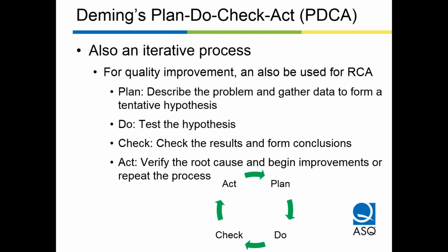And when I say gather the data, this may mean look at the SPC data out of production, statistical process control, what were the values produced over the last period of weeks, or look at the failed part itself. Form that hypothesis, or the way it often works is the team does sit down, they brainstorm, fill out the Ishikawa diagram, which for me is a collection of hypotheses, prioritize that first one you're going to evaluate, and test the hypothesis. Then check your results and form conclusions.